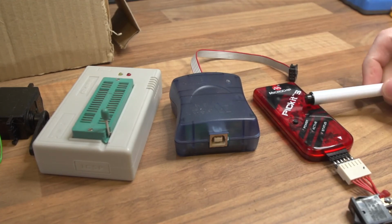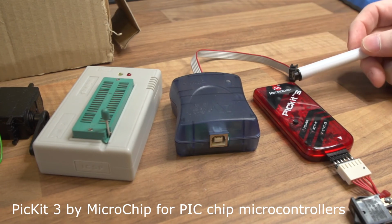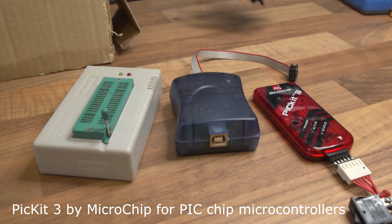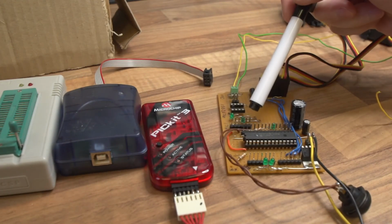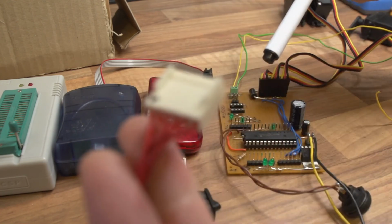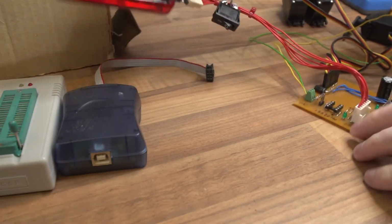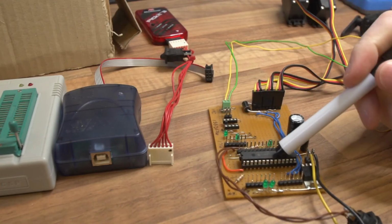This particular one is called a PICkit 3 from Microchip, and Microchip do their own range of microcontrollers, like the PIC I showed you earlier. And on this particular board that I made, you'll see that it has a single inline header, and that's a programming header for the programmer to plug into. So the programmer connects into there like that. That connects to the computer through USB, again with its own firmware, with its own software, and that programs the chip internally with your firmware.